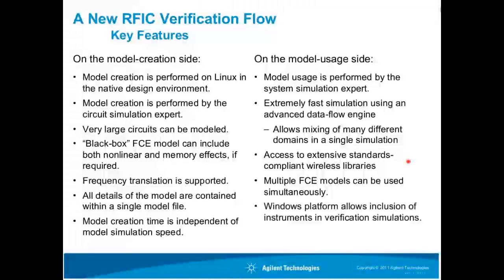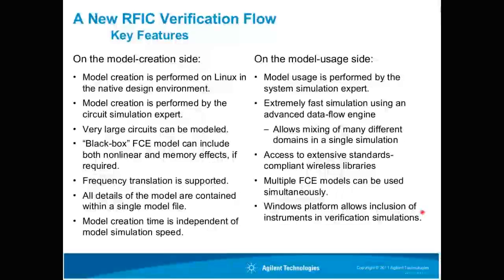And probably extremely important here is that when you're on the Windows platform, now you have the ability to run full instruments in your simulation. So now you can attach your VSA to the output of your radio that's running in the simulation, and you can demodulate in simulation time while you're doing things. So you can be tuning gains, you can be adjusting the modulation schemes that you're using, and see it all being handled directly by the instrument. So you'll have good confidence that when you get to the lab, you'll be able to duplicate the results that you have here.